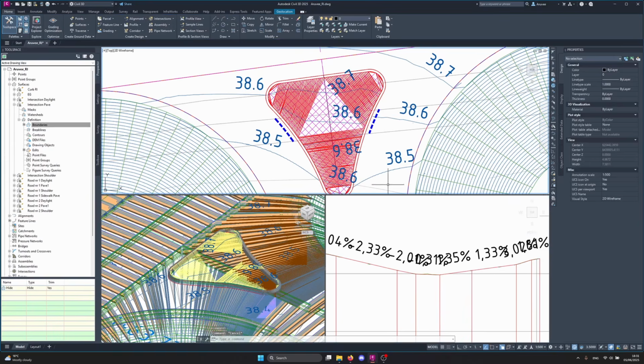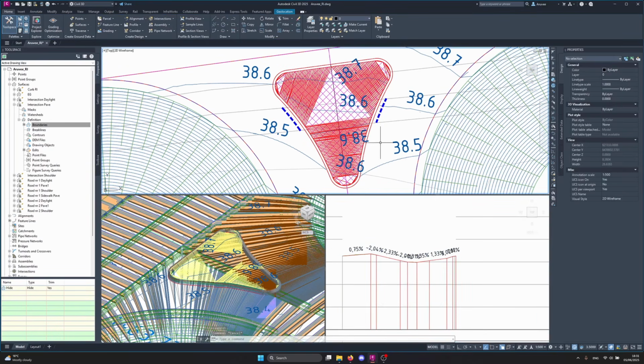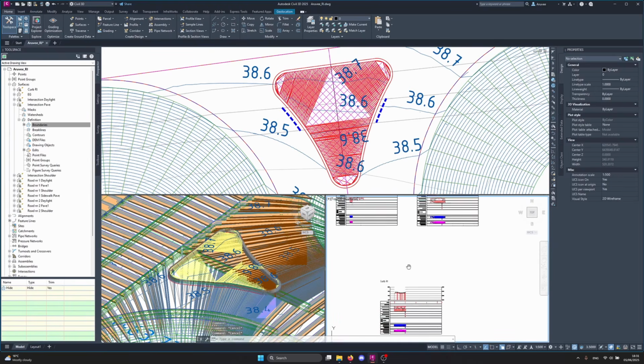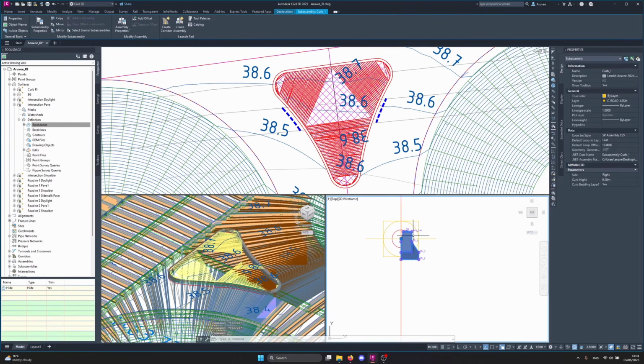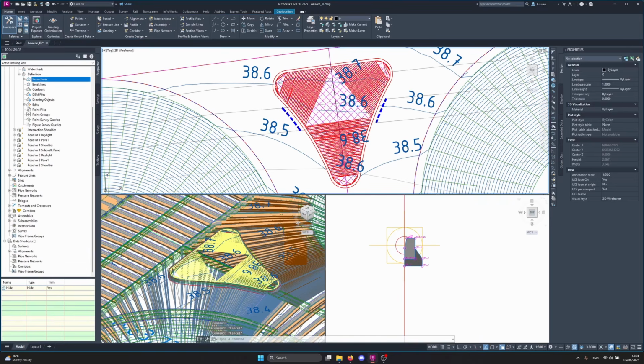And I just make a full circle, and from this profile I made a corridor, and I'm using just a curb sub-assembly, this one right here, simple as that. One thing to keep in mind is that this curb should have a curb height parameter. So just by default, as you can see, I can change the height of it, and you should have it as well if you want to change the height of the curb. And I will explain in a minute why you need that. So yeah, let's keep it 10 centimeters. Right here, let's rebuild it as well.